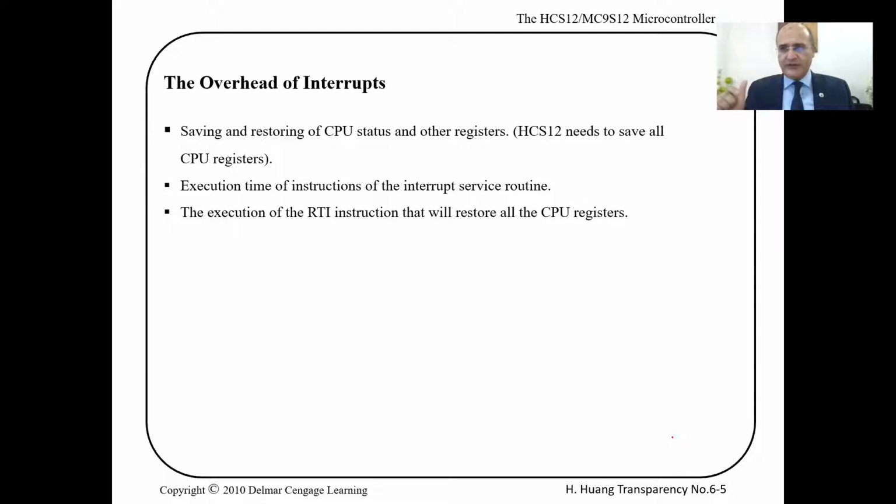When you press the button and cause the falling edge to happen on a pin of the microcontroller pins, this will cause the program counter to go execute some code you wrote in the interrupt service routine. Going to execute that code, going out of your sequence, executing that code, okay, and then returning back, how much time does that cost?